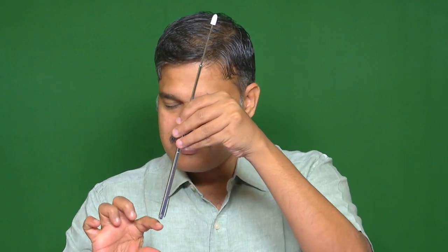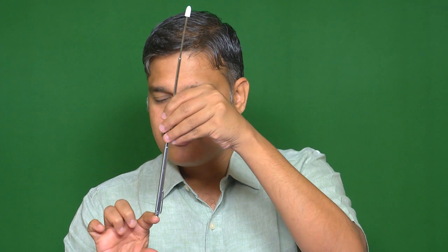The elastomeric bearings will not have much tension capacity, so the seating or shear key from the column will come out, and it will not offer any tension resistance. That's why base isolation is not suitable for tall buildings. It is suitable for short buildings, say 5-story to 10-story buildings.